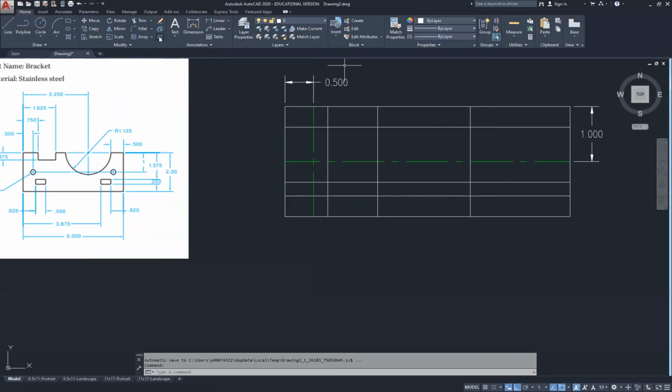So I'm going to go ahead and do an offset command. 0.5, enter. Select this line here and bring it across. I click enter. And that line that I just offset is also going to be my next center line here. So in the assignment, it does not show this dimension, but for the instructions coming from the instructor, make that dimension 0.5.